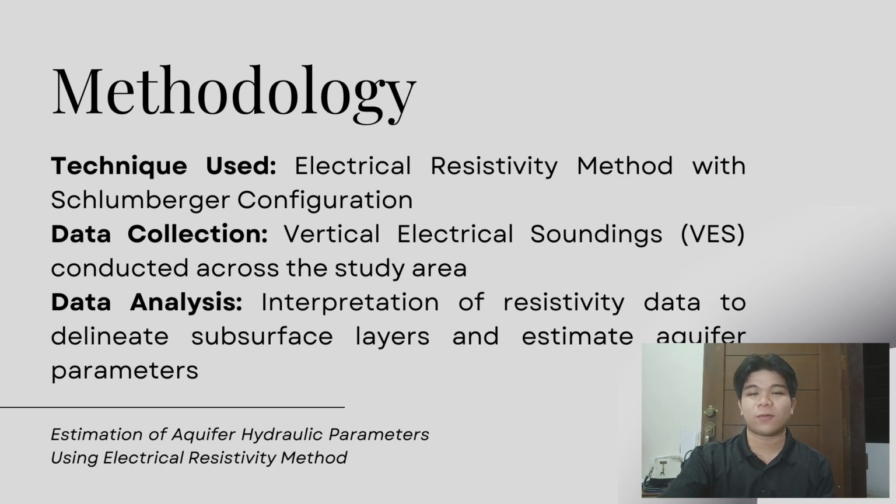The field data acquisition was carried out by laying electrical cables along predefined profiles, and the cables were linked to the ground using sets of electrodes and cable jumpers. An electrode test was performed to ensure that current was flowing through all the electrodes, and the inner electrodes are the potential electrodes and the outer electrodes are the current electrodes.